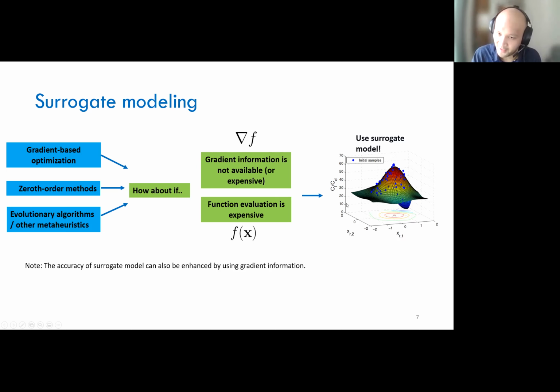So as you can see on the right figure, we have the blue points, which are our experimental design. We have our design variables, x1 and x2, and we also have our target or our objective function, which is CL/CD, which is the measure of aerodynamic performance. So we have several sampling points, and then we try to approximate that function by using this limited information. So that f hat is basically that response surface.